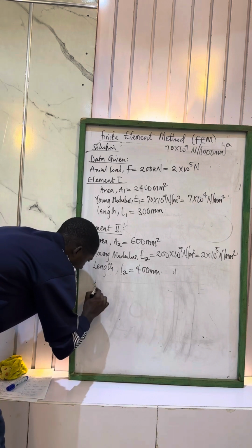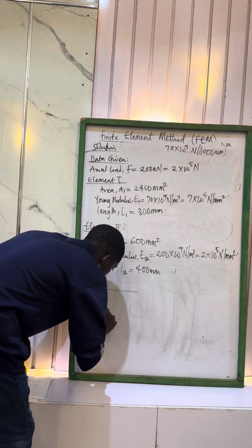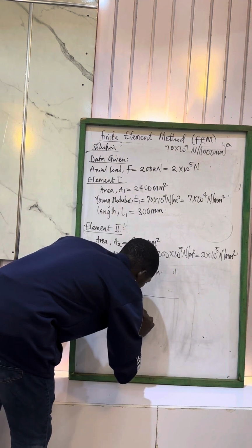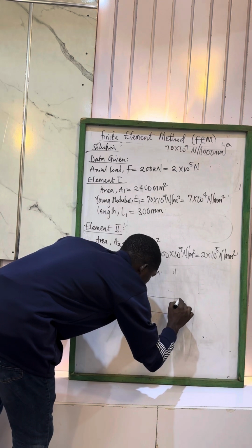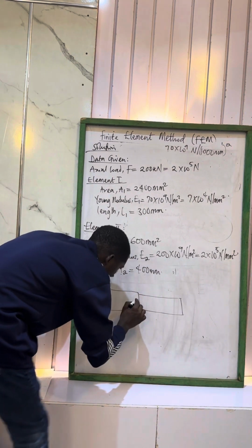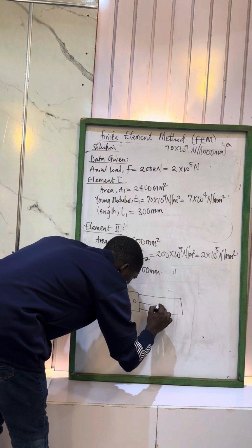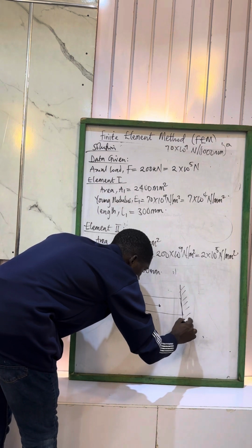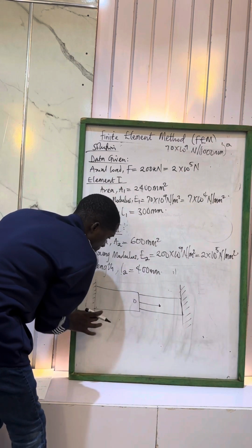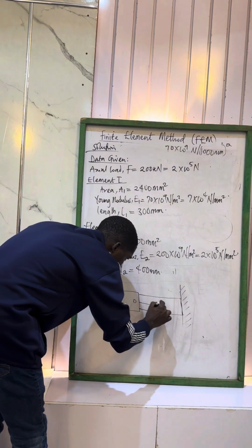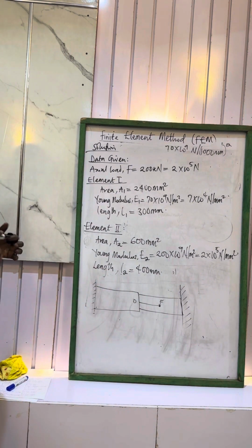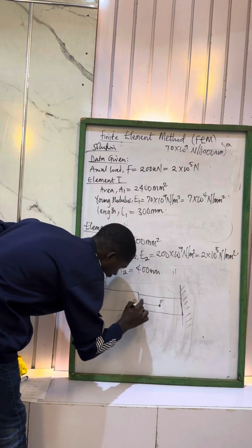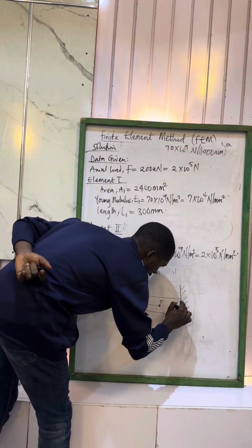So if you go back to the diagram, we have this, because now we have to do the discretization. At this point O, the force is applied here. And don't forget that this also is sectioned, so we have a block here and another block here. The force here is F. Now, let's section it, that is, we're going to discretize it. There's going to be a point here, which is node 1, another node there, which is node 2, and another node there, which is node 3.